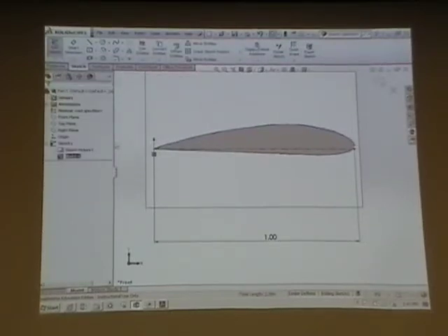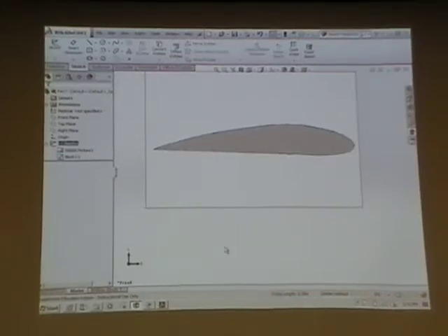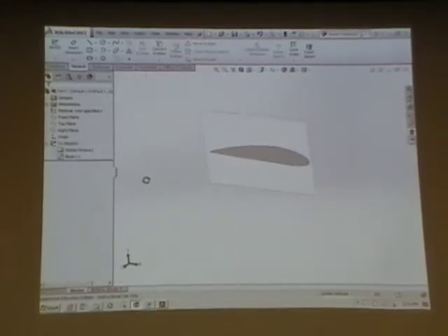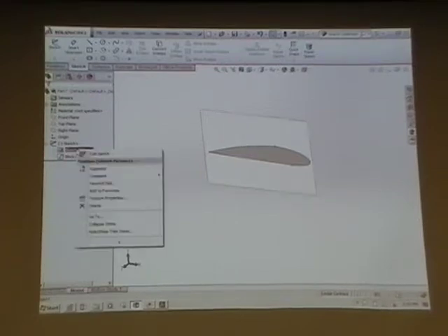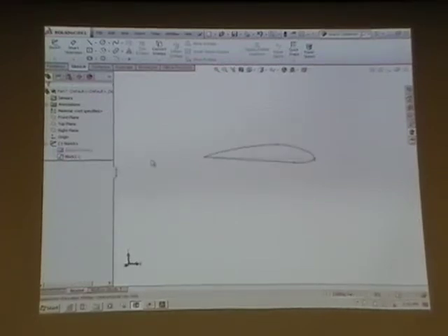Okay, so that created the sketch block. And you see it now listed over here as block 1-1. And I will accept that sketch. Now, if the picture is in your way and you want to hide it, over here in the sketch 1, you've got the sketch picture 1, that's your picture. You can just right click on it and suppress it if you want that to go away. And then you're just left with the sketch itself.